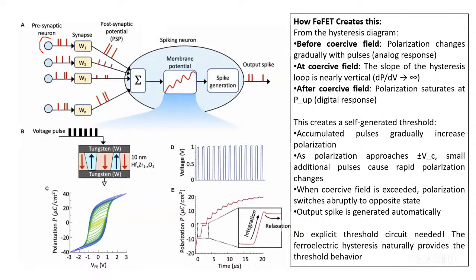So what happens in a ferroelectric FET, if you give a pulse inside the gate stack, you have these independent ferroelectric domains, or we can say uniformly polarized areas. These uniformly polarized volumes are going to be used for changing the state of the neuron. And as the spikes come, these smaller spikes are going to basically go for minor loops.